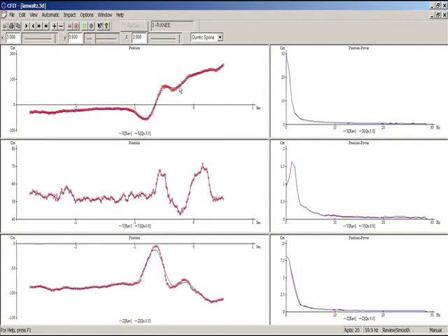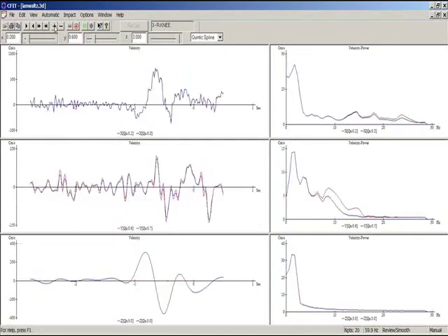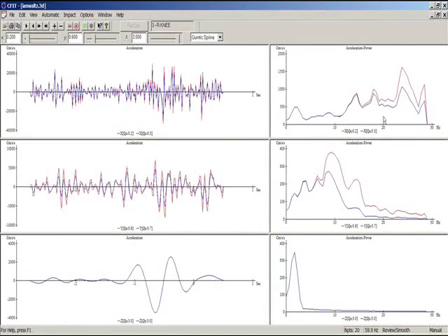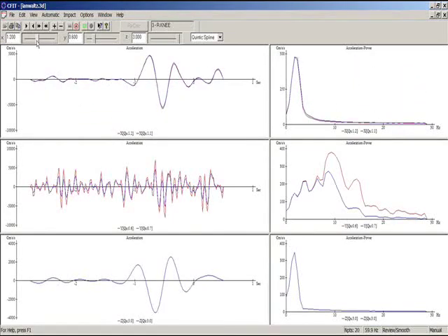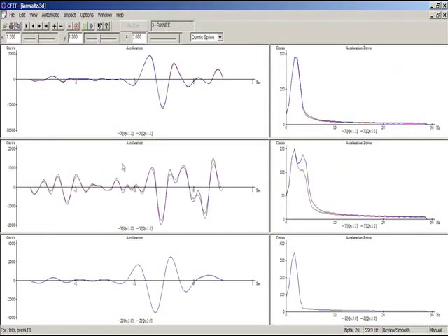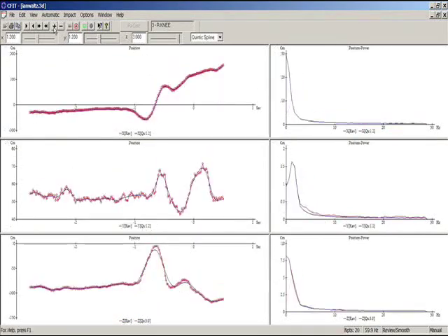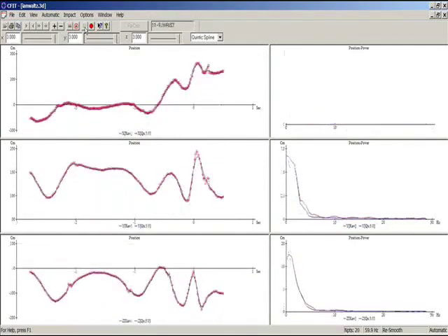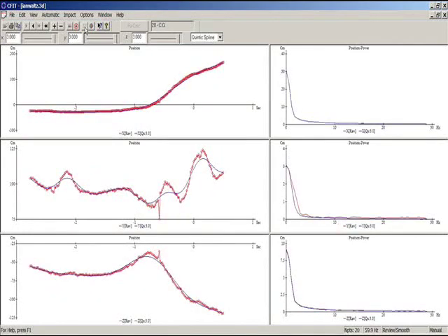If we take even this segment, which is very well smoothed, and we unsmooth it, it looks the same. However, if I go to the acceleration, look how much noise there is. Also, you see on the power spectrum here, a lot of high frequency. So we always have to remove the high frequency to get the real data. Same thing to do on the Y coordinate and the Z coordinate. I will not spend a lot of time here on the filtering. I'll go back to the position, and it will automatically filter all of them. We'll have another discussion about the filter module by itself.